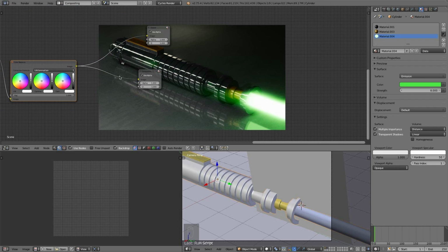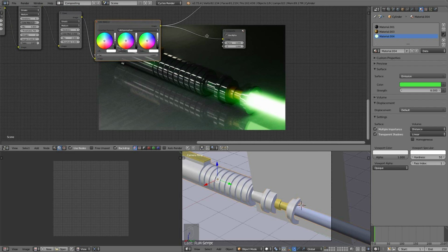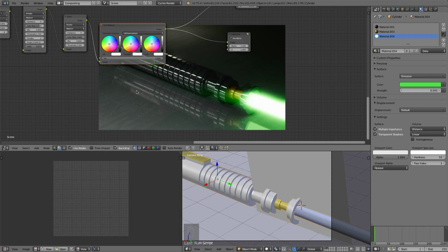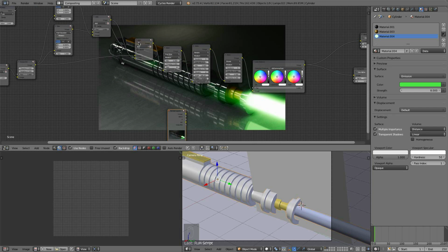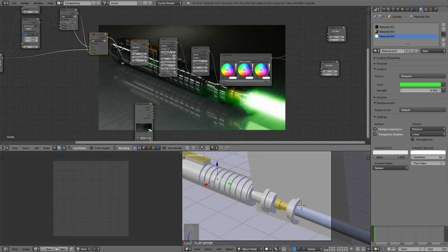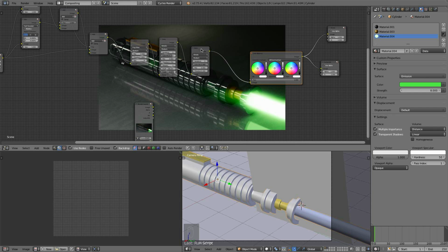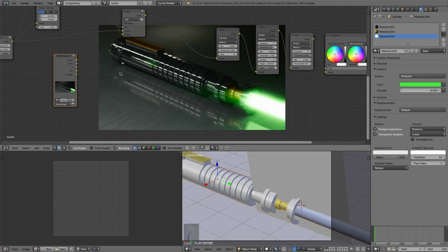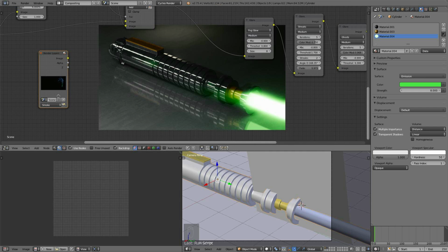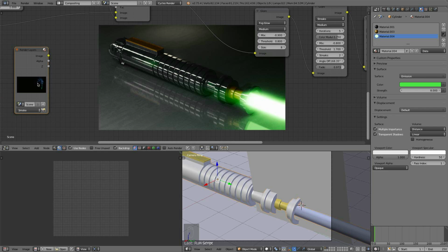And one last thing I almost forgot is we got to add that little touch of smoke back in. So what I'm going to do for that is just add in a basic render layer by going Shift A, Input, Render Layer. And I think I'll add this in back before the glows here. So let me just give myself a little bit of room here by moving the glows and glares down a bit. There we go. And I'm going to switch this render layer from the basic render layer over to our smoke render layer. And you should be able to see just black with some smoke.